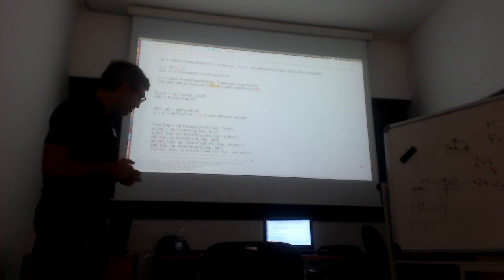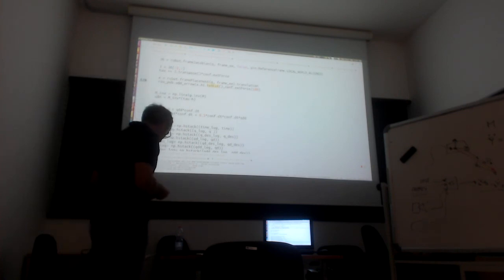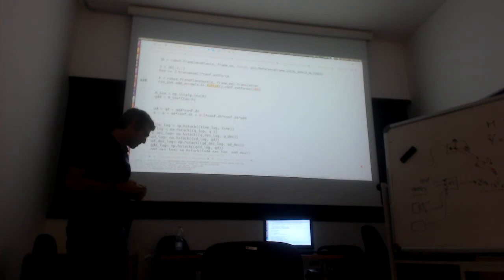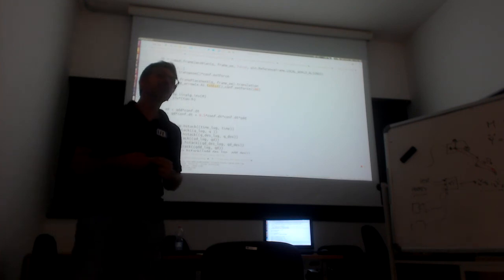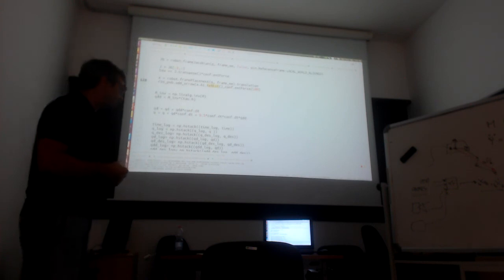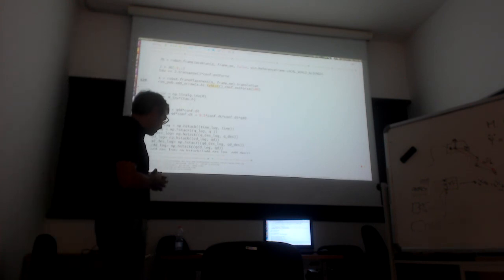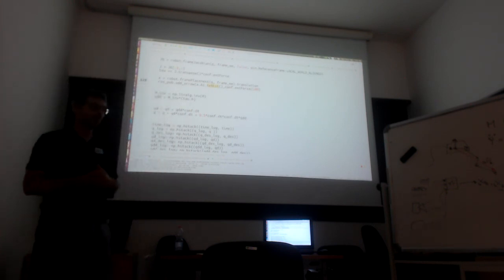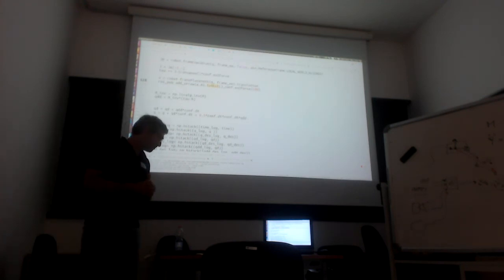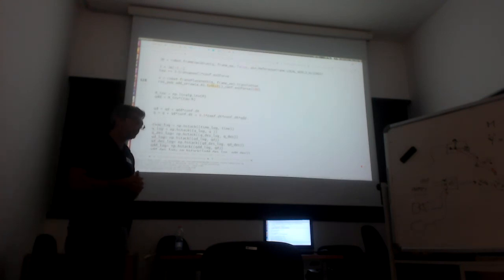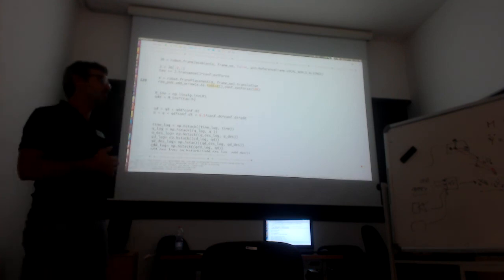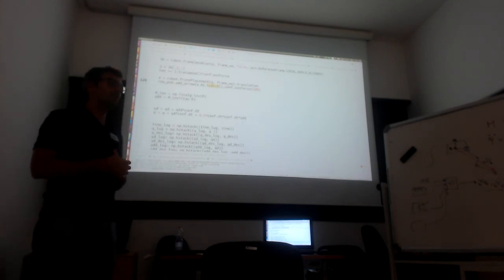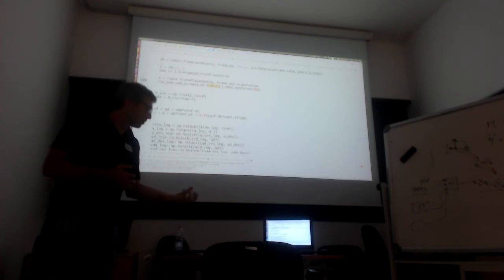And finally, we moved to discuss the dynamics of the manipulator in contact with the environment, showing that the contact force enters the equation via the Jacobian, and the different kinds of contact that can be established with the environment depending on the kind of contact surface.